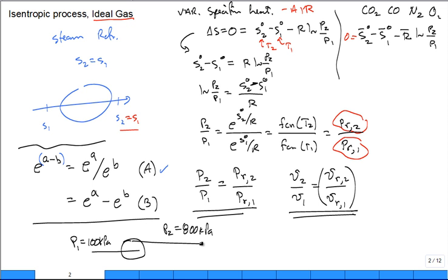Okay? How would I get it to be isentropic? It's well insulated, no heat transfer, hence no entropy transfer with the heat, and it's reversible, no entropy generation. One inlet, one outlet, no heat transfer, reversible, it's isentropic. Does that statement make sense to you?